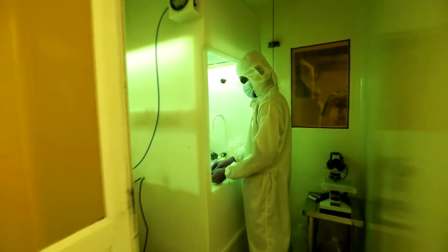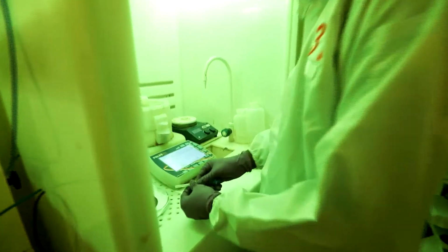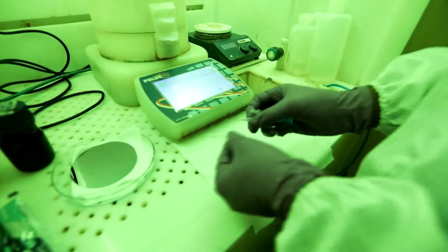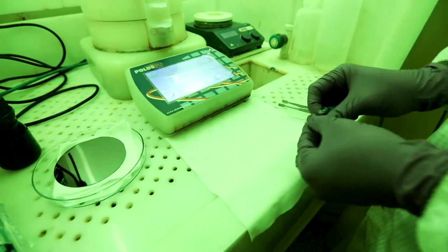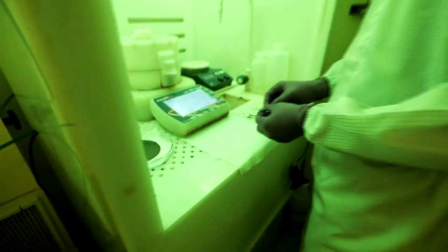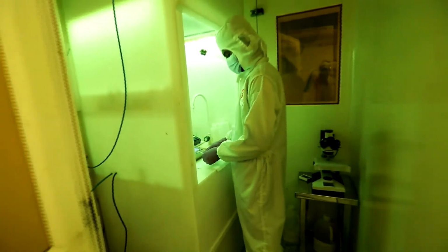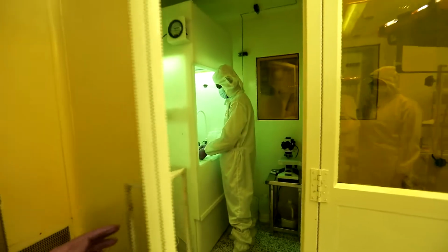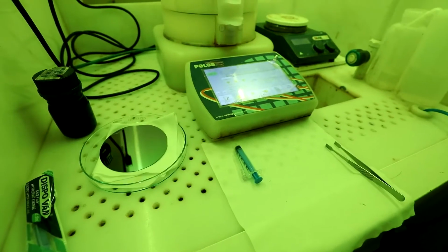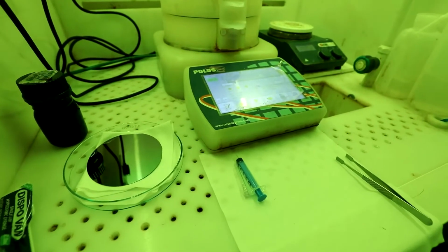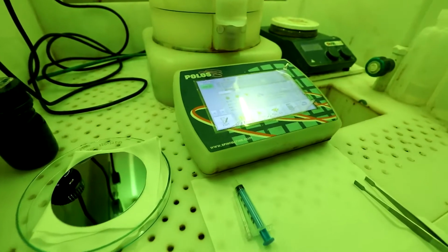There are three basic process steps to transfer a pattern from a mask to a wafer, that is, spin coating of photoresist, exposure and development. Let us start with a spin coating procedure. Spin coating is the procedure for making very thin films of photoresist onto the substrate.